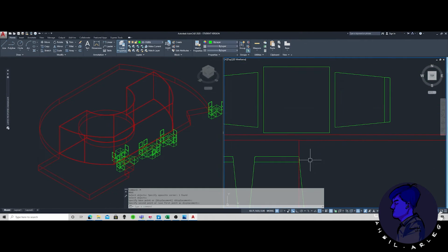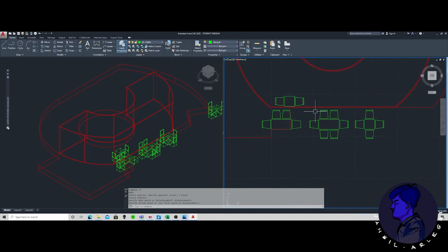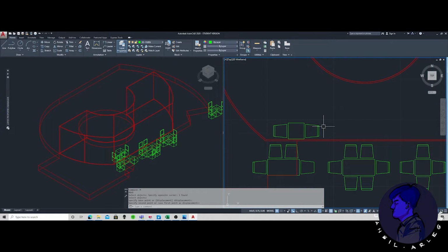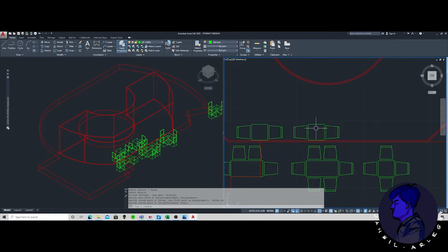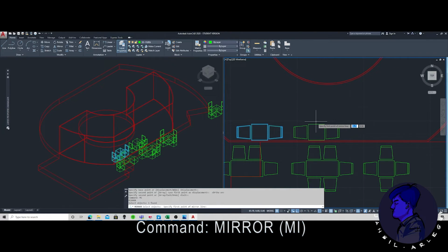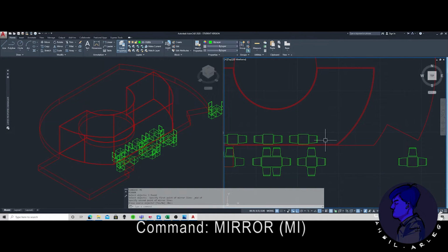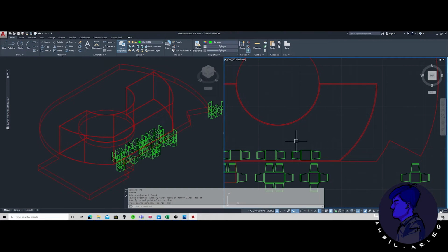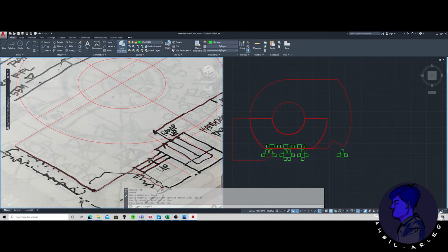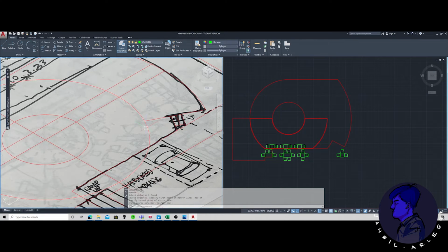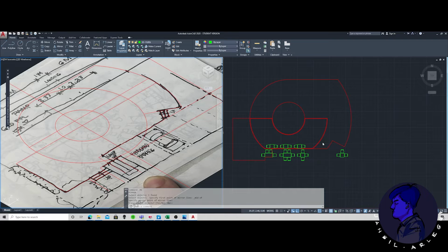Just place them in. This is going to be the glass window here, and this is going to be the parking. I'm just gonna move, and I'm just gonna be copying them. Copy a few, and then here I'm gonna ortho lock that for ample space between those 2 chairs, so that's not too tight. If you want a more accurate, uniform layout, I'm just gonna mirror them. And then there's going to be checking the sketch. The door is gonna be here somewhere.